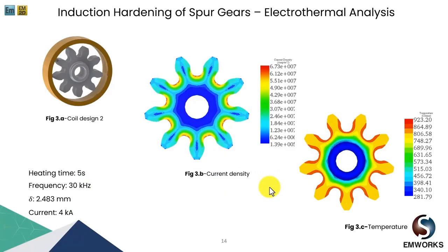So it follows the tooth profile and achieves the required heating rates with an average of 800 degrees Celsius for the desired depth. So this design solved the symmetry issues, even if the maximum, where the red zone, doesn't cover all the teeth contour, but it will be improved later when playing with the material properties.